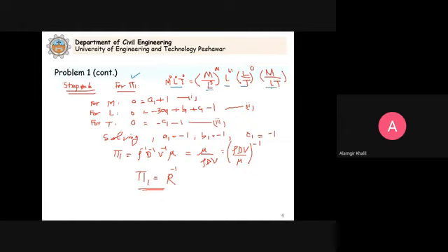So you put the dimensions, and as I said before, the methods of dimensional analysis that we discuss here, what is the basis? The basis is the principle of dimensional homogeneity, which is written PDH in your textbook. So what is the principle of dimensional homogeneity? That the dimensions on the left hand side of the equation must be identical to the right hand side of the equation.